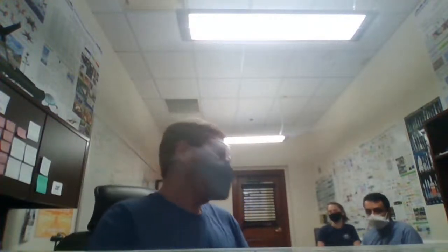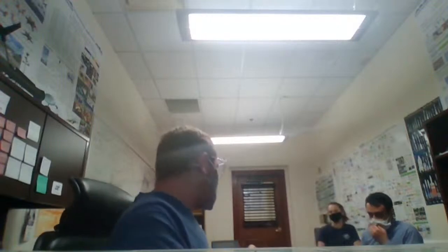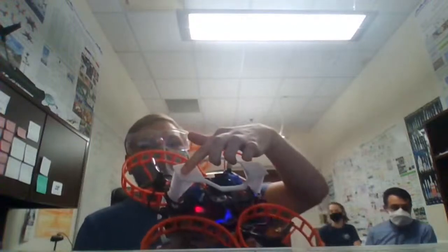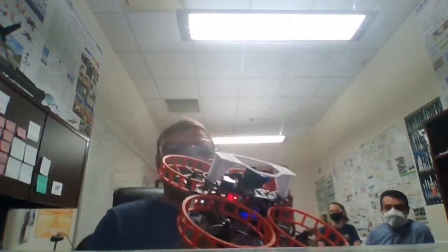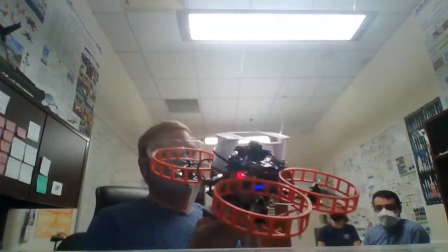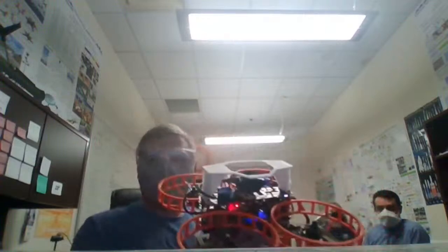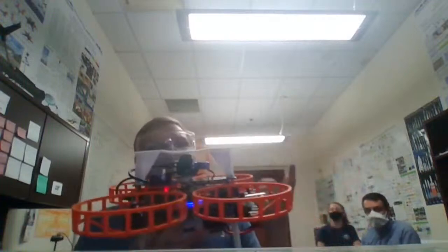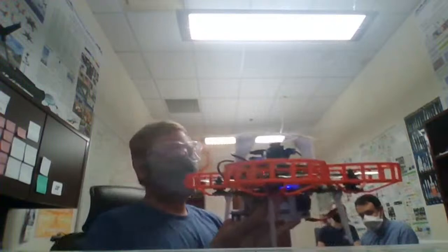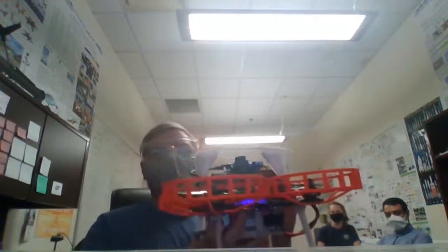So the part that isn't complete on this drone here, and I'll just pull it up here, is the top section doesn't have any way to attach to the larger fixed wing. That's because I'm building everything on this small quad rotor first, and then I'll design the other parts that it attaches to later. The reason we went with a thermal camera on this instead of a regular camera like you can see me on is because we're hoping that it can see high contrast of the ship that it's supposed to dock into against the background of Mars, since it is very, very cold there. And maybe dust would get in the way of a regular vision camera.